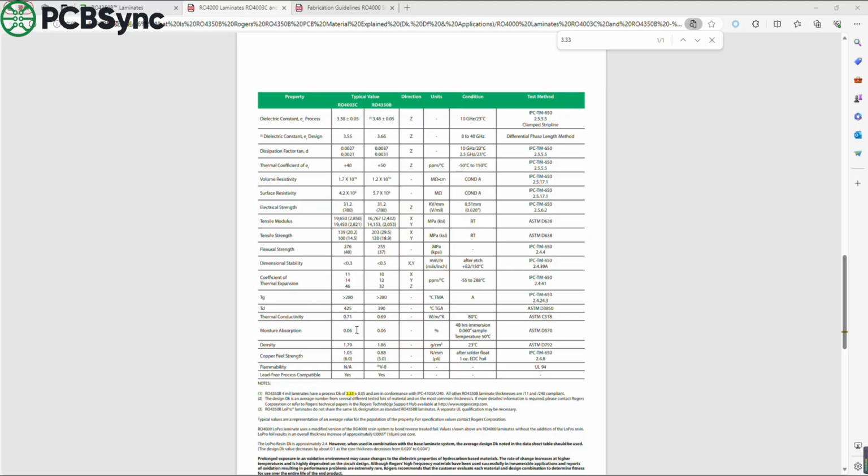The standard thermal conductivity of RO4350B is 0.69 watts per meter Kelvin, measured at a temperature of 80 degrees Celsius. Thermal conductivity indicates the ability of heat to transfer through the board material. The higher the value, the better it usually is for dissipating heat from localized areas to the surroundings. However, the actual temperature rise of the PCB is also related to factors such as copper layer area, copper thickness, thermal vias, device packaging, metal base plate, and external cooling conditions.